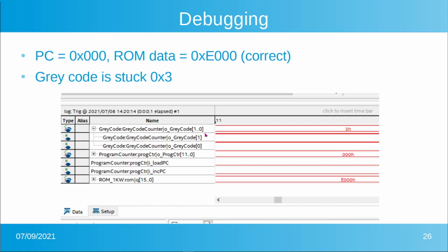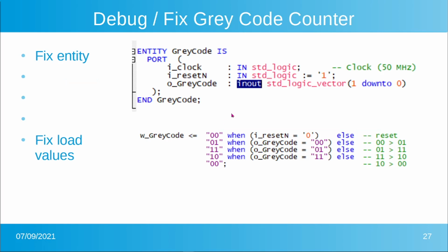I think I mentioned it. I'm going to do something for that error. We had these set to W gray code, so what was happening is, because this isn't a clocked entity, those bits would just rip all the way up to 1 and they would stick there. So let's change that to the output, which is the latch version of them. Then this will only change and set the preload for the gray code at one time.